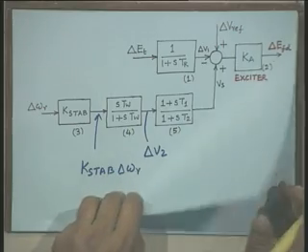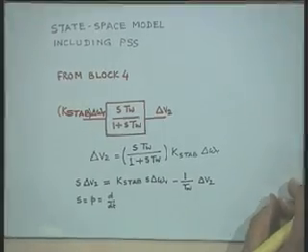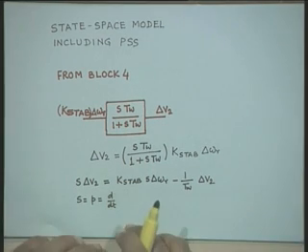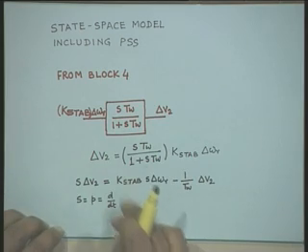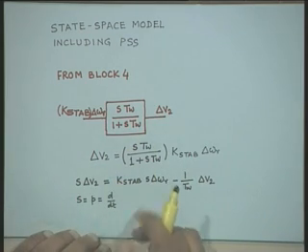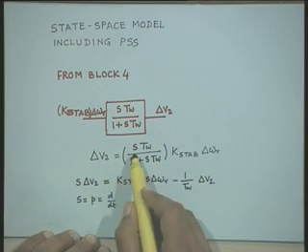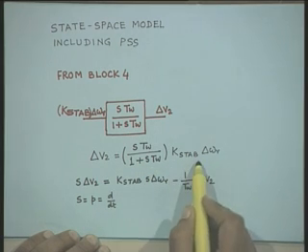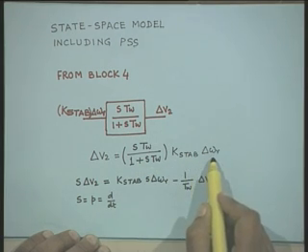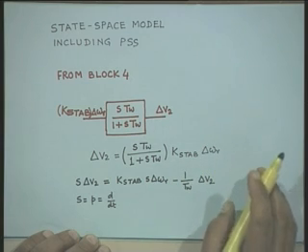A similar approach is to be used for deriving the additional state variable equations, right. I will just illustrate for delta V2 also. Now, to develop the equation corresponding to this washout block, we can write delta V2 equal to S Tw over 1 plus S times Tw. The input is K step into delta omega r. Delta omega r is a state variable.